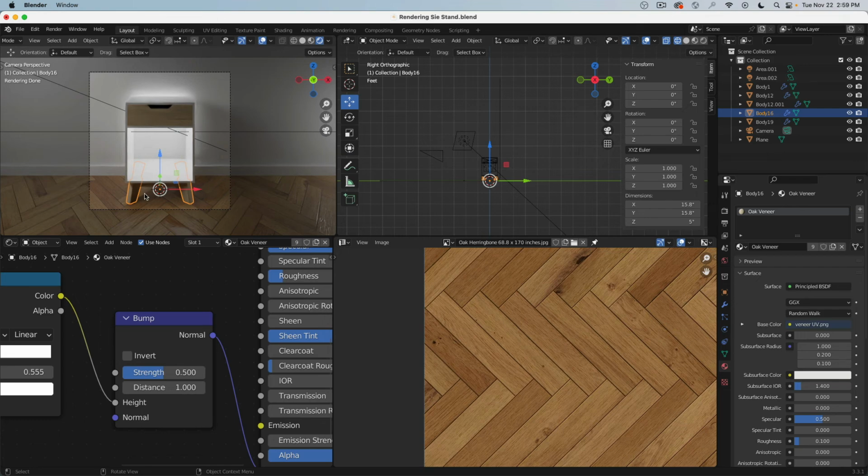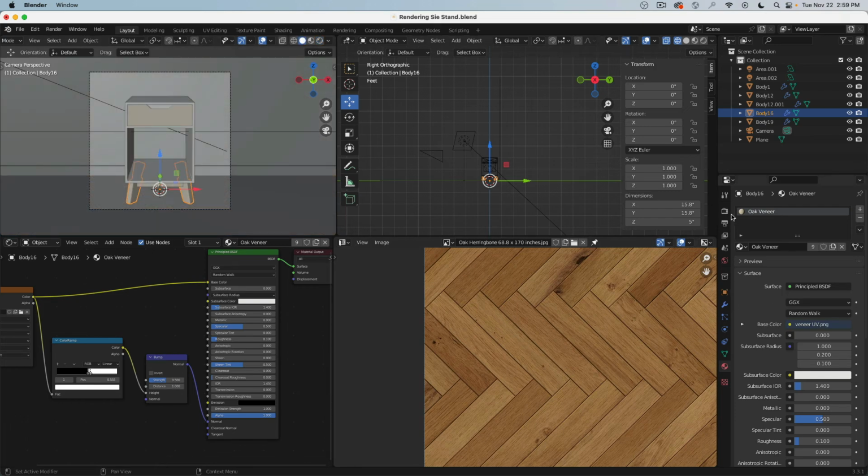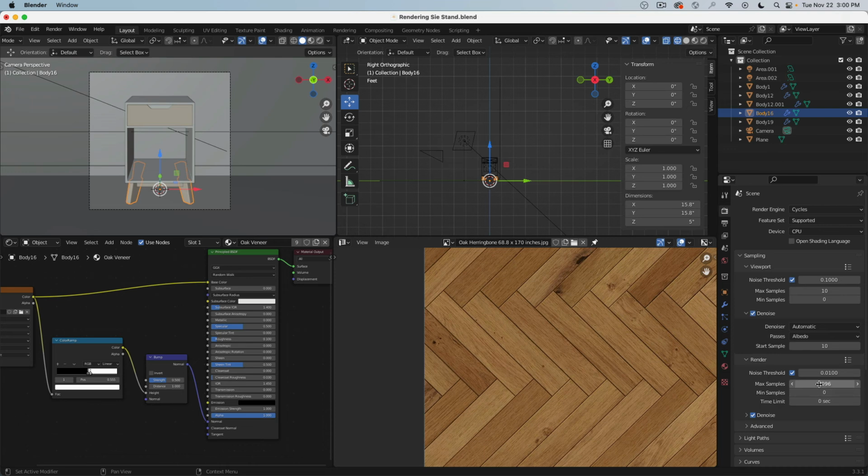To do now a nice rendering, we can stop the rendering here. We can go to there. Because of the fine materials, we also have a denoiser which can kick in. And there's no best number here for the max value. Maybe 100, we can do a test rendering and see how this works. 200, 400. Now you have to see what value is time-wise still doable and at what lower value the denoiser starts blurring out the textural details.